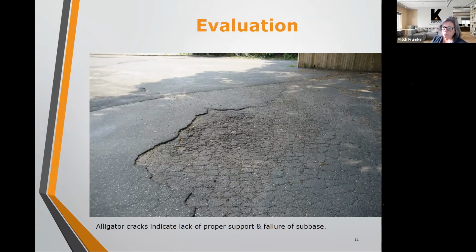And you have the same problems that you have underneath. They don't go away because you put an overlay on it without milling and without proper repair and preparation. So in this particular case, you could see where the overlay just broke right off of the original problem.